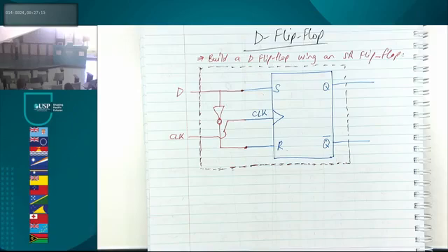So this is the, check this out. Inside the SR flip-flop, what is there? The SR latch. You add some more gates, what does it become? It becomes an SR flip-flop. From the SR flip-flop, you add one more gate. In fact, this NOT gate, is it possible we could have built it using a NAND gate? Yes. All right, so you can build this entire thing using NAND gates. All right, anyway, that's just a back-end story. The true story is this.